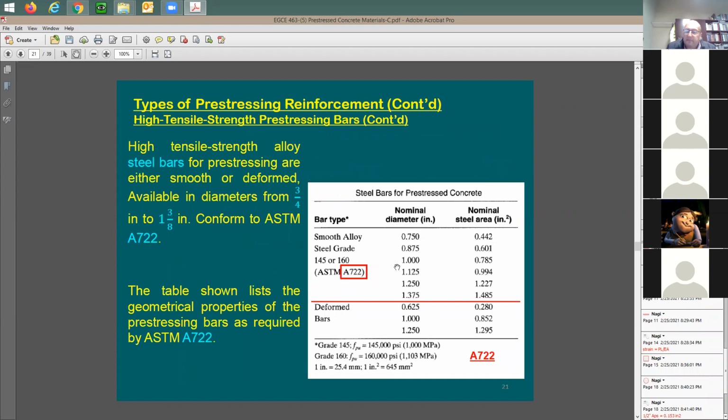Now the rebars. If you recall the rebars, I told you about the Dywidag bars. It's usually large size. It starts at what? 0.75, 3/4 of an inch. The very famous size that people would use outside is going to be this guy here, 1.375, 1 3/8 inch. It's going to be a good size, right? To use. Very famous. They call these Dywidag bars. For the other bars, you have 3 sizes, like almost 5/8, 1 inch, 1 1/4.